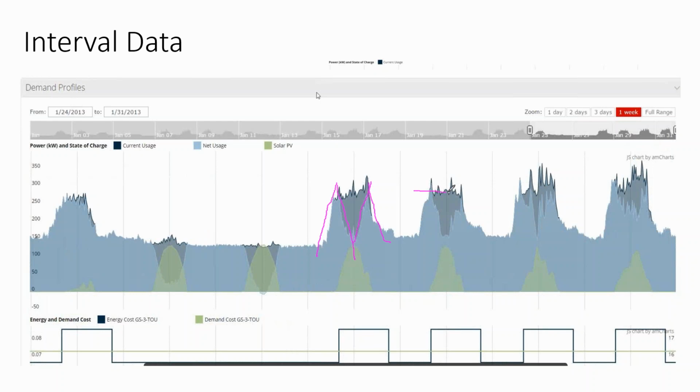So what used to be a relatively flat curve is now spiky. And it could be that the most cost-effective solar array is one that just goes and shaves off the very tip top of the peaks of your power curve. I like to say that this is mountaintop removal for your electric bill. And so we charge our battery in the valley, and then we use it to shave the peaks off of our load profile. Those are the most expensive hours of operation.